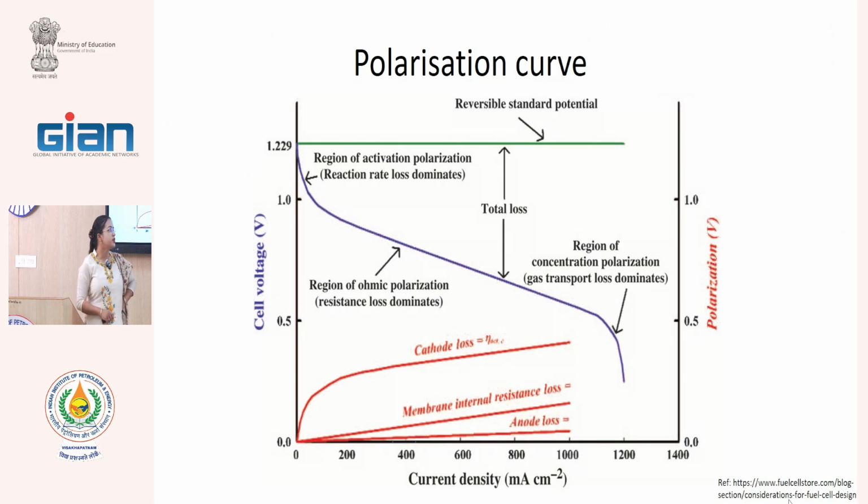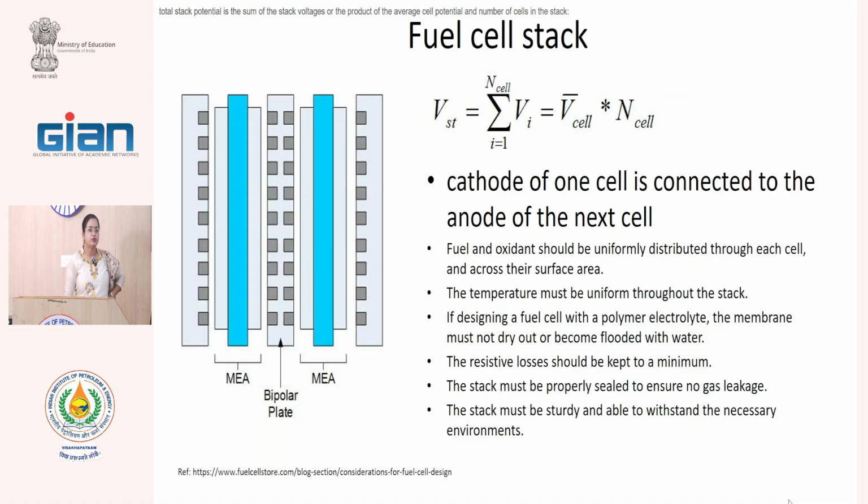Also, if there is very high mass transport resistance, this drop will be very sharp. If your membrane is good, you can expect the slope of the straight line to be smaller, a flatter line with less difference between the two. So this is one of the aspects by which we determine how your MEA is working.